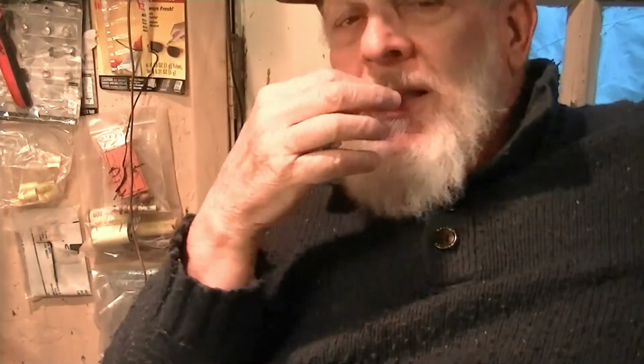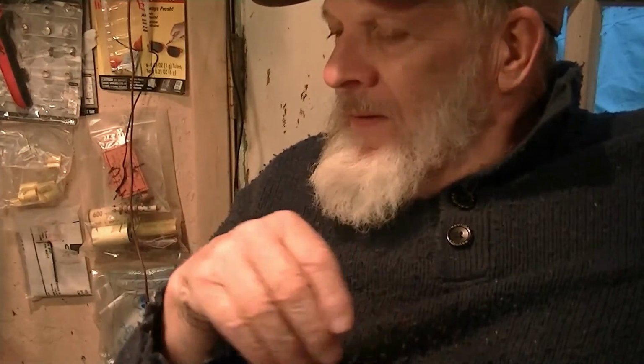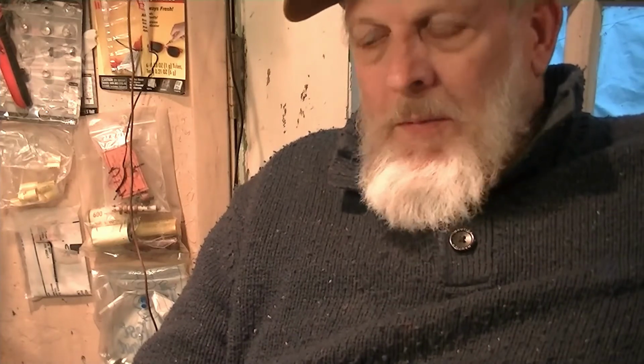And so very quickly you can find out if those basic things are working, and you can locate a malfunctioning tube by measuring the grid voltage of each of these 4 tubes and see if you find a tube that's wonky even though it tested okay. That's certainly the case in my radio. I've tested all my tubes with a good Heathkit tube tester, and I'm still having AVC problems.